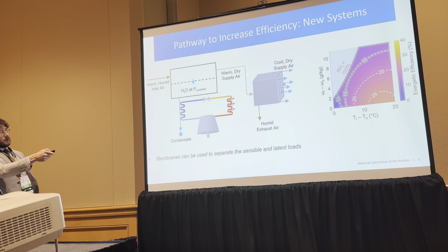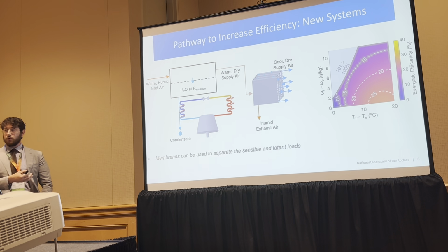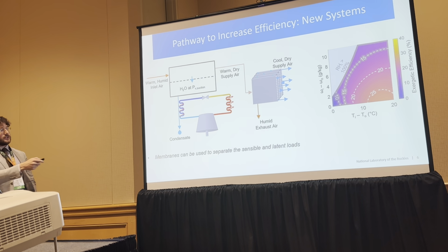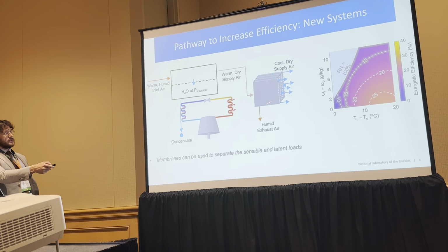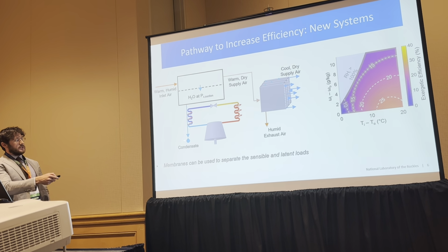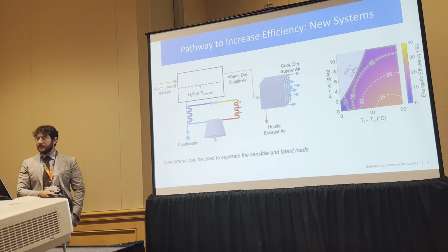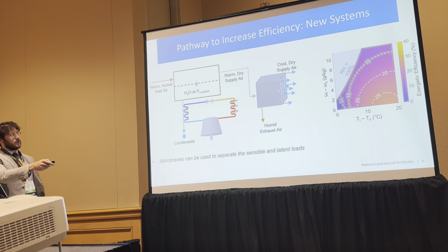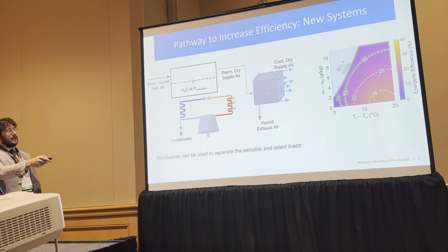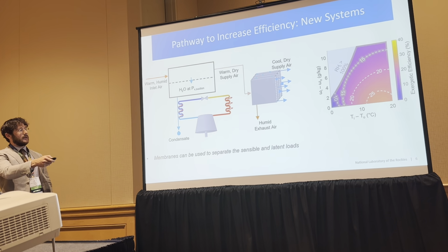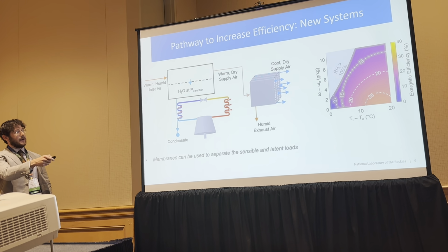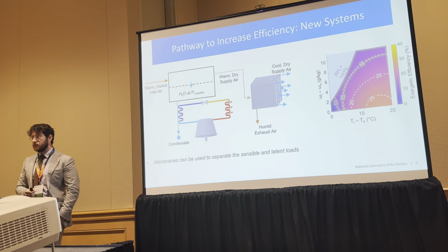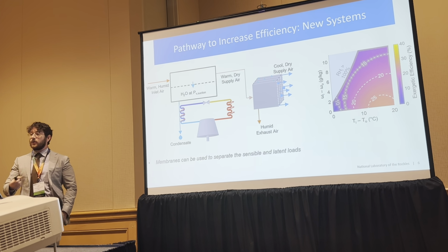And so we could use another vapor compression cycle to then cool off our air for the sensible cooling, but we're producing this condensate over here, so what if we reuse that to improve our efficiency? So we looked at modeling an indirect dew point evaporative cooler over here. So we take this condensate, we use that as our water supply for the evaporative cooler, and the way that it works is the air goes through, it's pre-cooled through a heat exchanger, and then a portion of it goes back through and evaporates water on the other side to produce cooling, and is then exhausted as humid air. But then a portion of that initial pre-cooled air is just taken off as our supply air to our building. So we're able to cool our air without directly humidifying it.